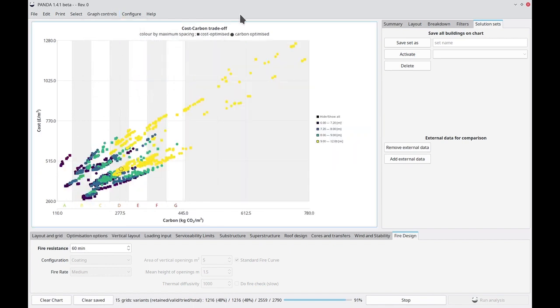Column spacing is a very common driver. Of course, larger spans imply more carbon. And we know that, of course, as engineers, but it's useful to be able to put a number on it. And we can see here that going to very small spans has the benefit that it allows for those softwood joist structures here. So that's one of the reasons you might want to have smaller spans. But for example, for steel or concrete structure, the effect is not as large. However, going to much larger 9-12 meter spans has a big impact on cost and carbon.